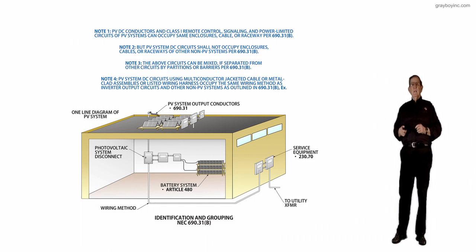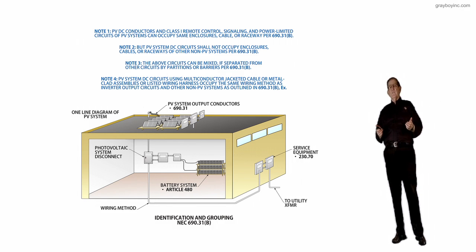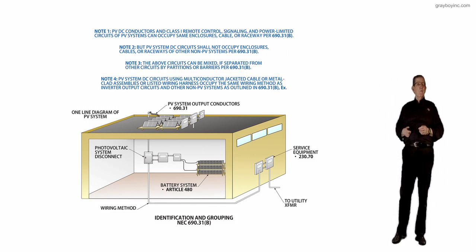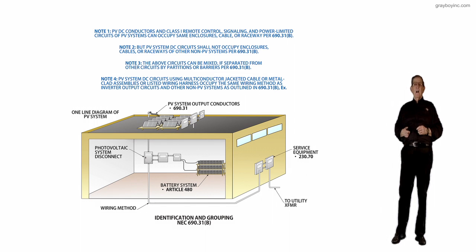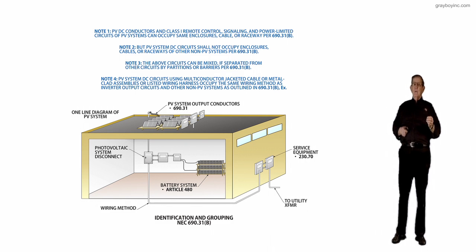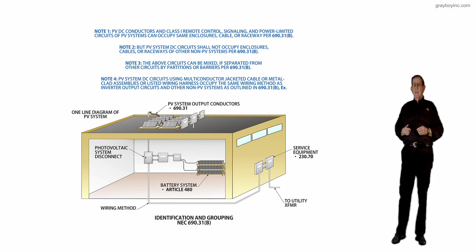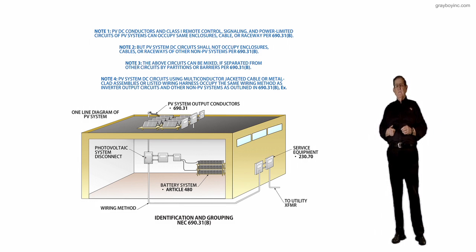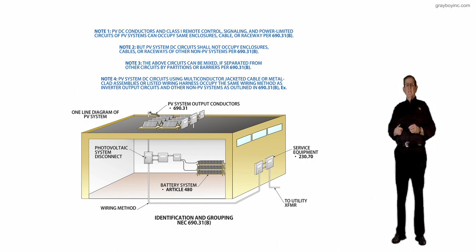But notice the PV systems mounted on the roof could be series for a certain voltage, or could be parallel for certain current ratings, or both. It depends on how the system is connected and what is desired for the equipment supplied by this PV system. But notice 690 is a different article than 691 for utility type PV systems, very large systems that are listed there. So once again, I caution you folks that design and wire and maintain these systems of 690.